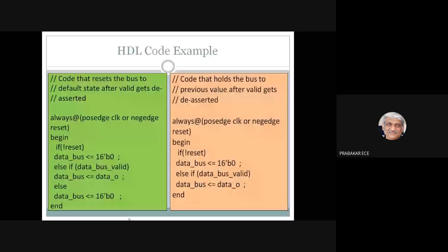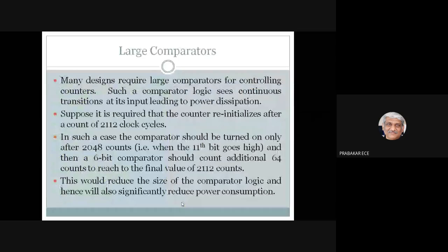But normally what happens is, because of this register, whenever there is a clock, the transition occurs, and the dynamic power consumption will be there. So an unnecessary register is there, and for every clock the register will be operating. So the total dynamic power consumption will be very high. And the static power consumption also is high because there is an area increase. So instead of that, what you can do is write the condition for if true and the condition for if false. If both the conditions are written, then the system will not assume a register there.